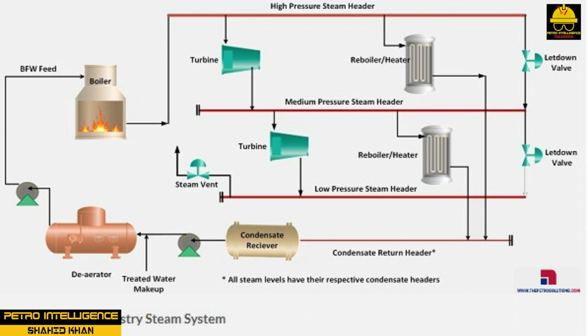Extraction steam and imported steam flows are regulated to maintain the header pressure at 400 to 800 psi. The pressure of the imported steam supplied through a pressure control valve is slightly higher than HP header pressure. In order to maintain pressure and steam balance in the medium pressure steam header, a letdown station is provided between the HP steam header and MP steam header.